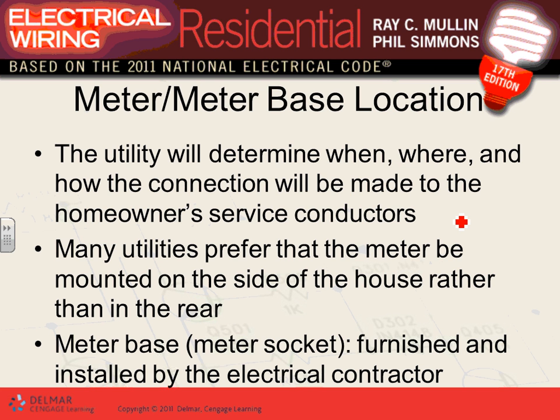Okay, utilities. Back to the utilities. Where do you want to put the meter and the meter base or meter socket, guys? Determined by the electrical utilities: where and how the connection will be made, and the owner service conductors. So the utilities will decide where the service is going to be. Like in dwellings, guys, it will be on the side of your house, through the service disconnect means and the meter socket, and from there you power your house.